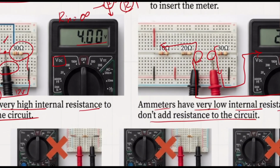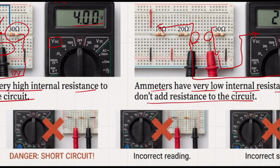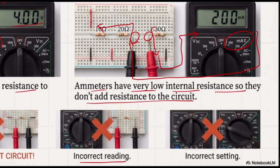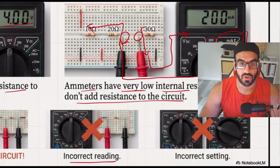A very common mistake is the short circuit. So be very careful. I will tell you how we can have the short circuit problem, and also about incorrect readings. It means that you do have the positive and negative sections. Sometimes you're going to connect them backward and you're going to read negative rather than positive. By the way, when we are talking about positive and negative, we are talking about the positive and negative in voltage drop and current.